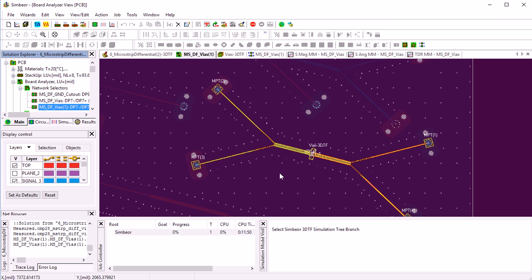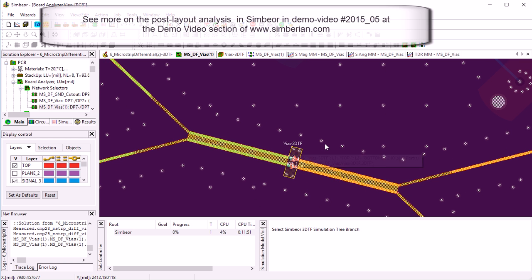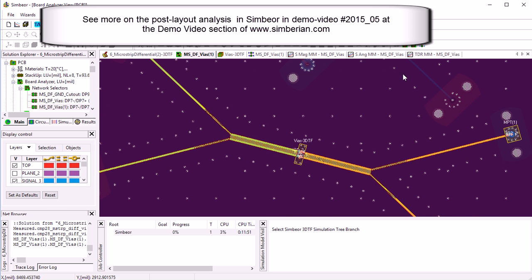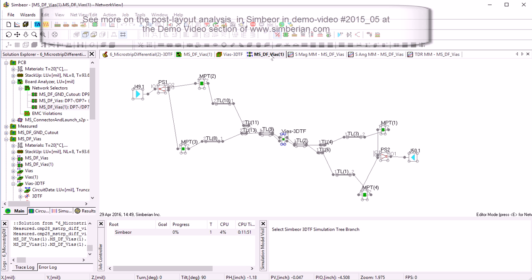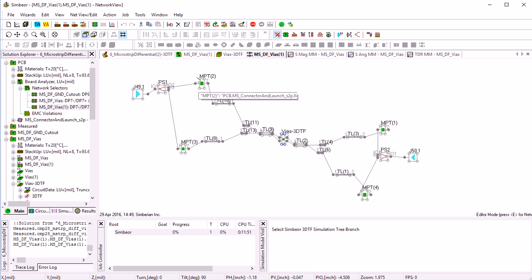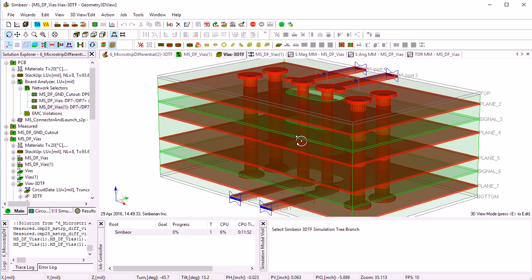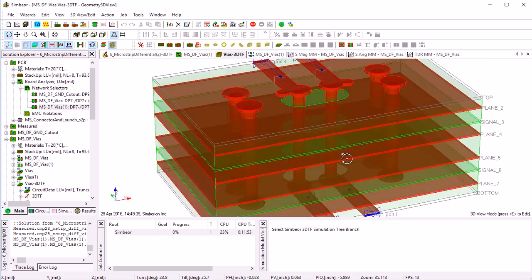With models for transmission lines constructed with Simbeor 3D solver and models for viaholes constructed with Simbeor 3D THz solver. The geometry was extracted into a circuit with discontinuities here. And discontinuities separately extracted and simulated in this particular case with Simbeor 3D THz solver. Those are vias.